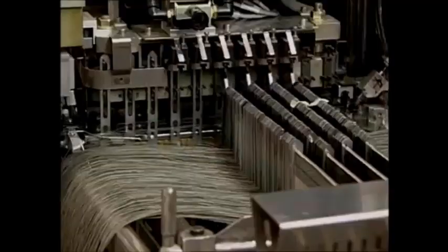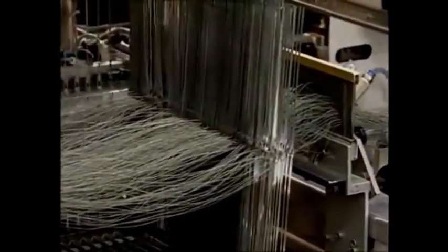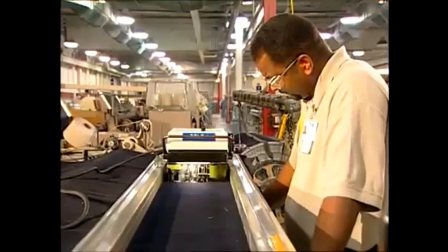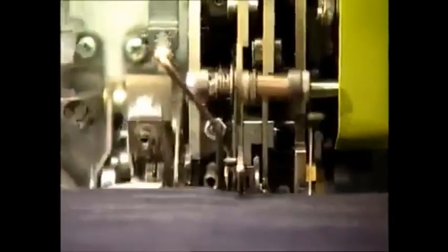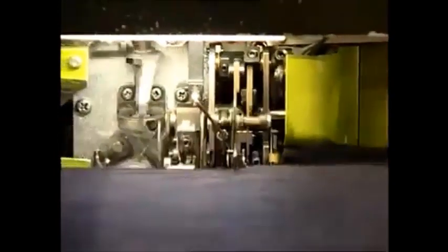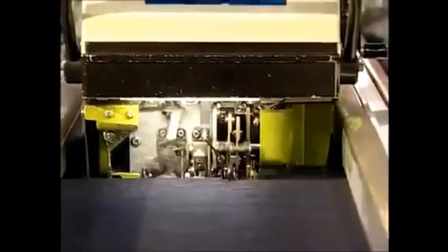When the same end count and draw is to follow on a loom with a depleted warp, then a full beam of yarn can be tied to the yarns of the old beam. This can be done by the use of a tying-in machine, which automatically selects an end of yarn from the old beam and ties it to the appropriate end on the new beam. This can be done very quickly with minimum loom downtime.